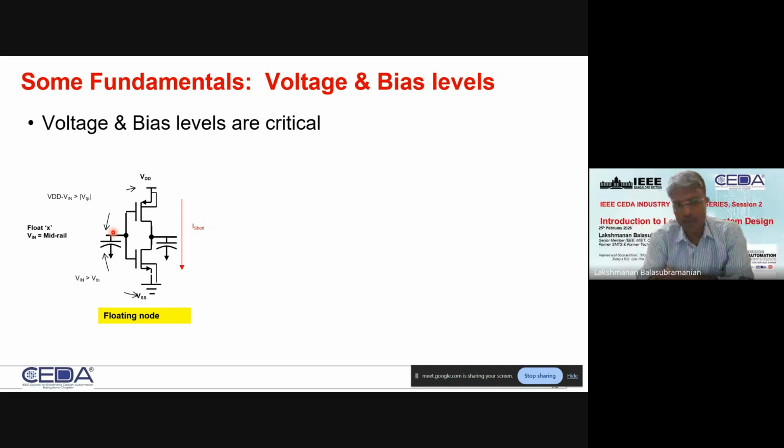What I want you to understand is, if the power supply is given, VDD and VSS, this inverter is appropriately powered, but if for some reason the input is floating, not connected to anything, there is no drive that puts this input in a known logic 0 or logic 1 state, either closer to VDD or closer to VSS within the respective VT of the transistors, or much away from them. If they violate all of these conditions, the input node can remain floating.